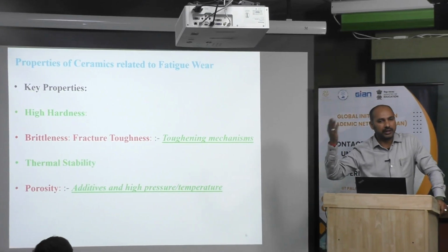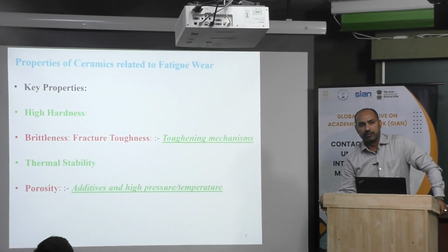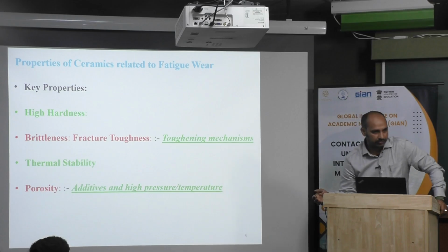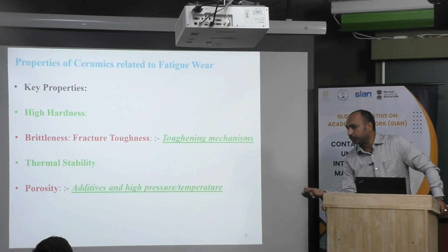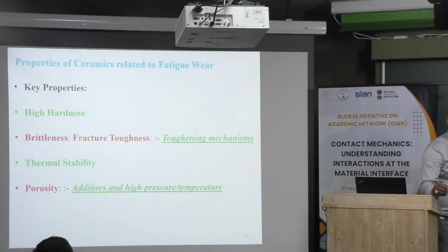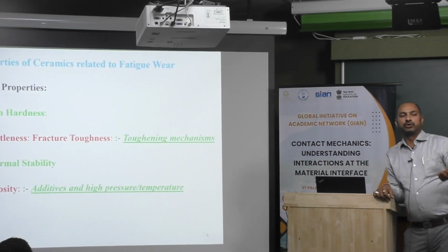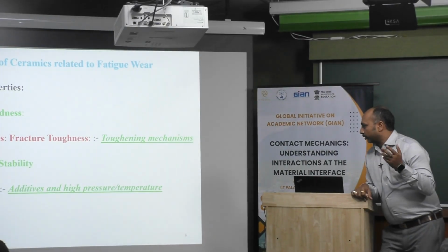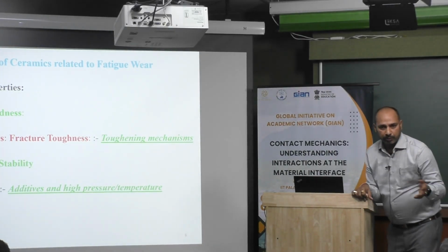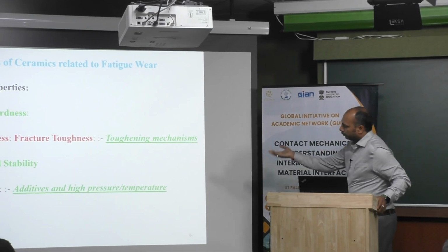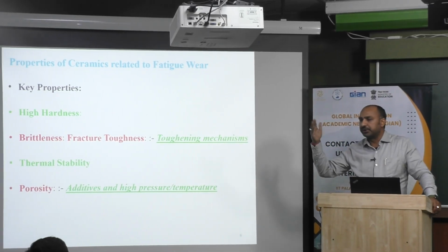Then they have very high thermal stability, which is very good for aerospace applications, some tribological applications, and critical temperature applications. Then porosity, as I told you, they already have some porosity, so that can be reduced by using additives, different types of liquid phase sintering, or by going for high pressure, high temperature conditions.